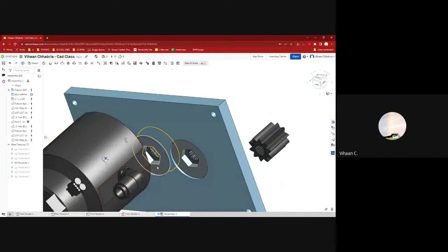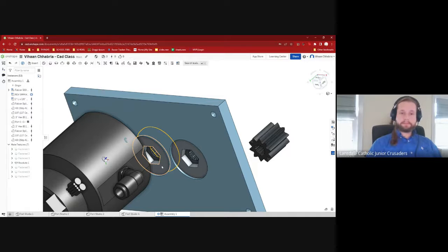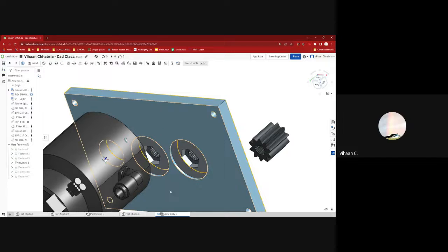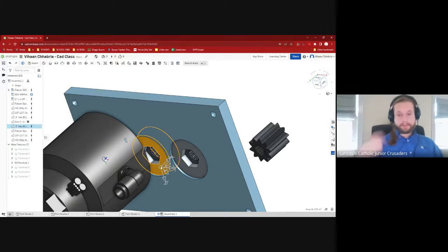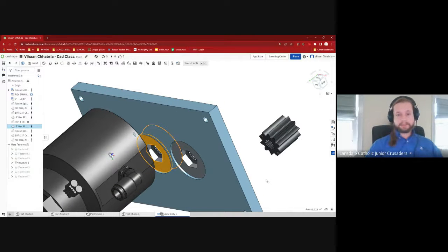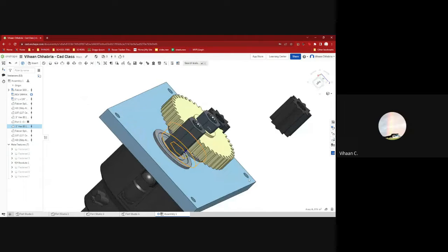Isn't there the bearing here? Yeah, so you want a revolute mate. You can also do a fasten mate to the bearing and then a revolute mate on the bearing to the plate. There are a number of ways you could do it. Sometimes it's not even important that these things rotate. Sometimes it is okay to just make fasten mates for everything.